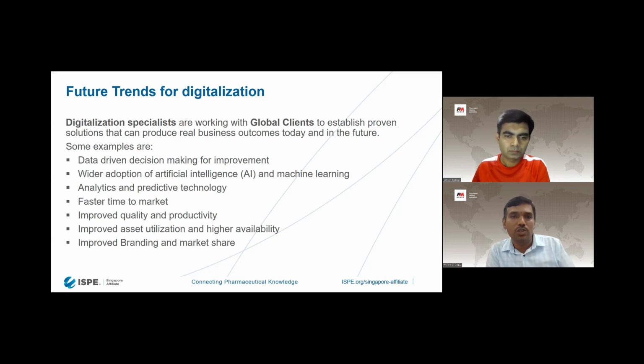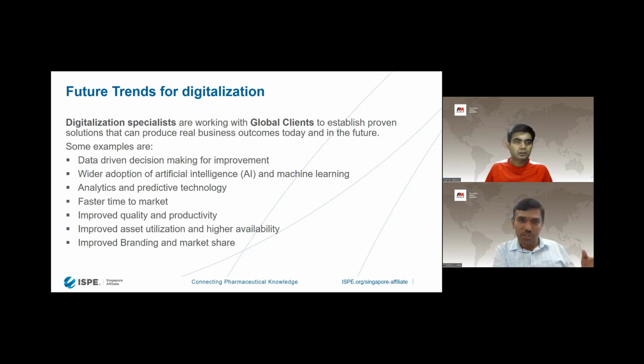Predictive technologies are there, as Sanjay also clarified just now. For example, we have a critical equipment like an AHU serving our production area. The AHU control system just operates that equipment, but it is also critical for that production area. Because there are fans and other rotating equipment, we put additional sensors to monitor vibration, and to watch that the motors do not overrun, for example additional temperature sensors.